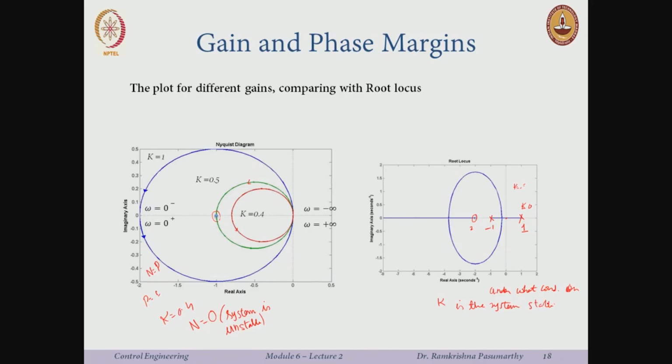Usually, okay, let's then do something else, right? Say I have a system with a pole at -1, a pole at -2, a pole at -3, and there are no zeros. And okay, I'll just do all the rules of the root locus. So one branch will go to infinity this way, and these two will meet here, right? So they go this way.